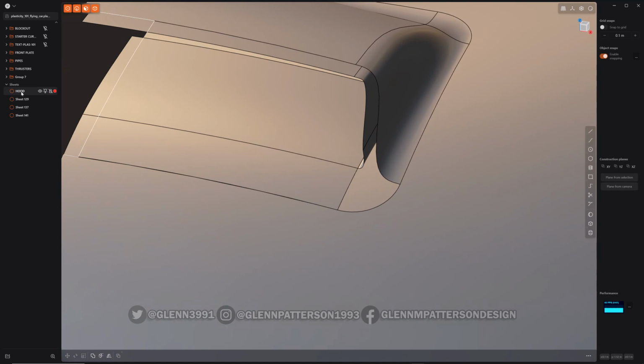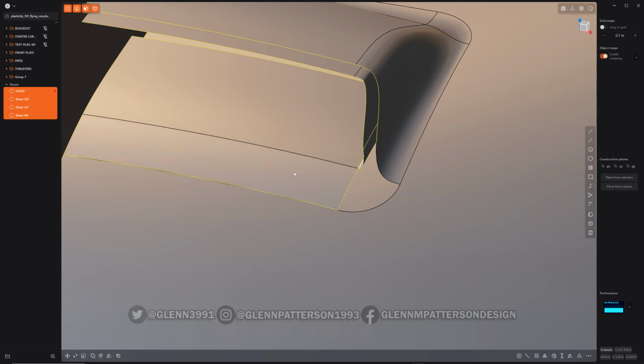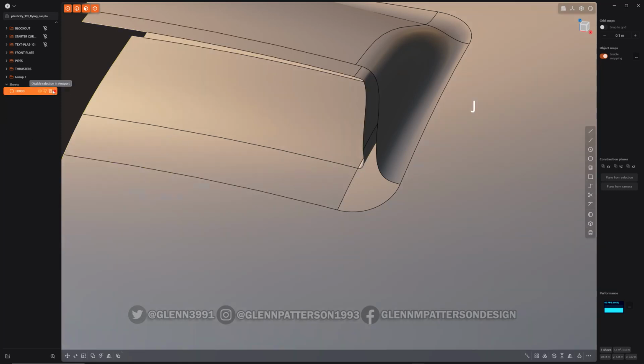So let's go ahead and select everything. And a tip, you notice how there's a material on here? It's got that red car material on the hood. If you select him first and then select everybody else and then join, that material will stay with it, even the name. So whatever the first thing is that's selected will carry over.